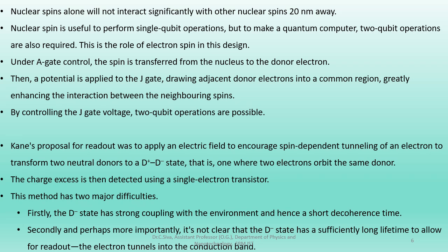For readout operation, Kane proposed spin-dependent tunneling, where an electric field forces an electron to tunnel to form a D+ and D- donor pair.